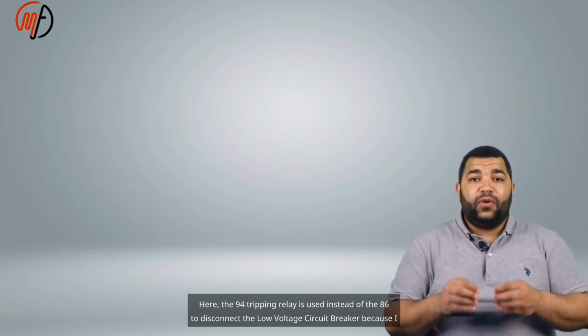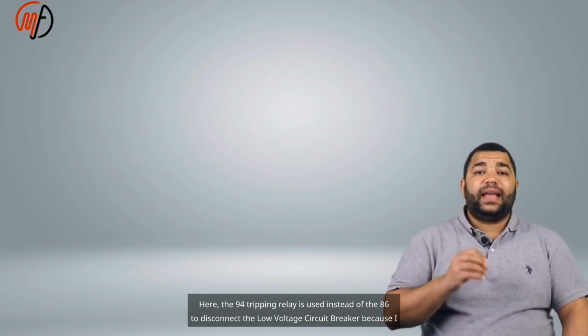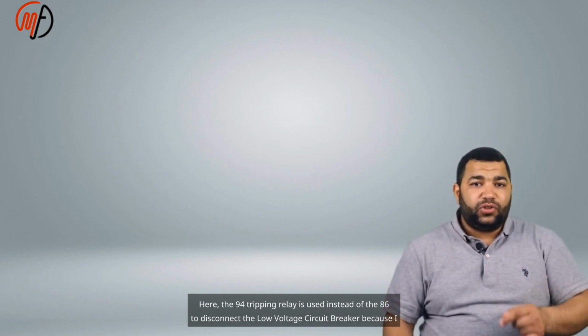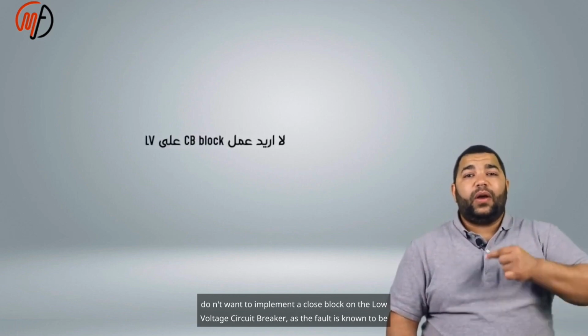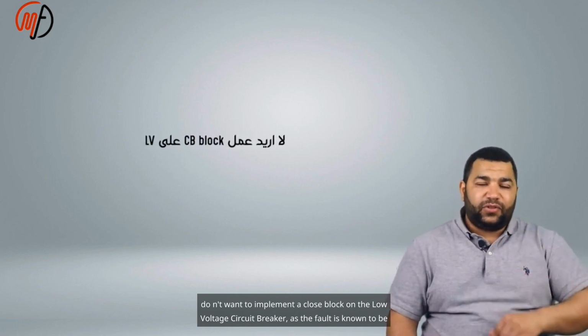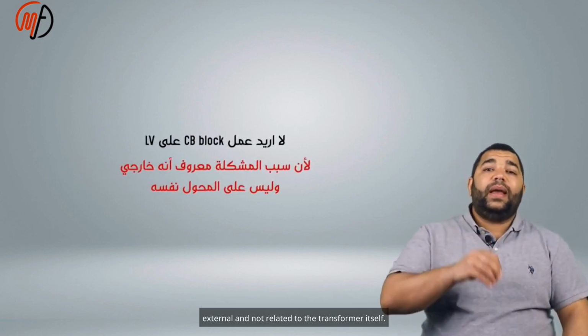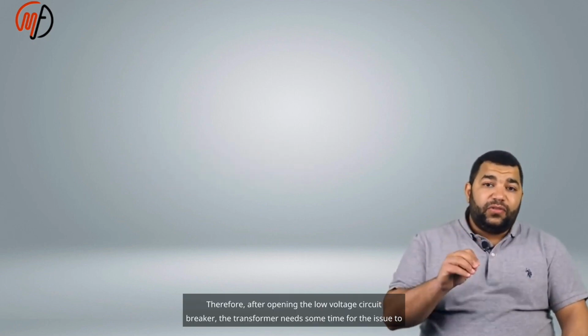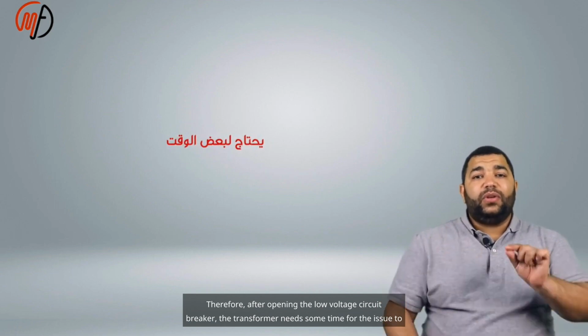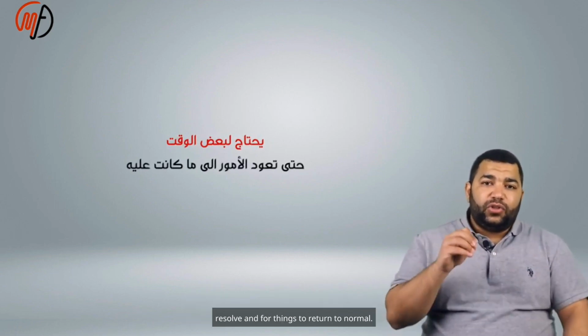Here, the 94 tripping relay is used instead of the 86 to disconnect the low voltage circuit breaker because I don't want to implement close block on the low voltage circuit breaker, as the fault is known to be external and not related to the transformer itself. Therefore, after opening the low voltage circuit breaker, the transformer needs some time for the issue to resolve and for things to return to normal.